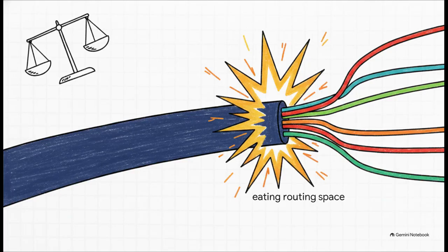Now, you might be wondering, well, why not just make the wire wider, like just use a bigger pipe? And yes, increasing the cross-sectional area definitely drops the resistance. But making every wire wider is a physical impossibility. For one, it eats up incredibly valuable routing space, but it also alters the capacitance and fundamentally changes how the wire electrically couples with its neighbors. It even affects the strict manufacturing design rules. So wire widening is a tool they use, absolutely, but it's a brutal, constant balancing act.